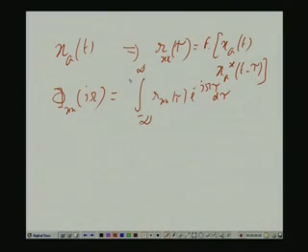Then, towards the end of last day's lecture, I was considering an analog, linear time invariant system with impulse response h_A(t). Input was a process X_A(t), output is a process Y_A(t). First we saw that the output also is WSS if the input is WSS, and then we found out the output power spectral density. I just repeat it today in case there was some confusion left that time, that will clear up.